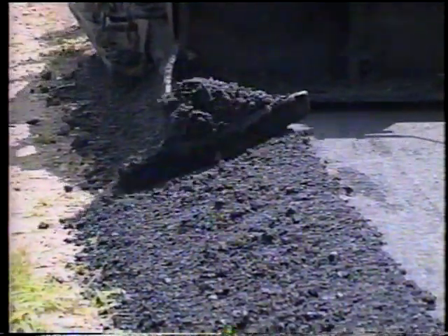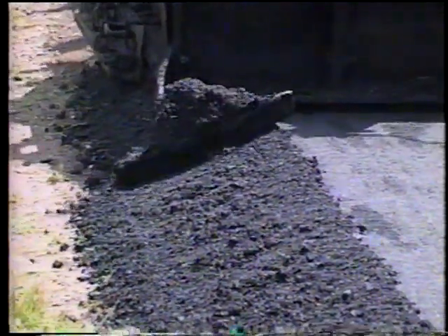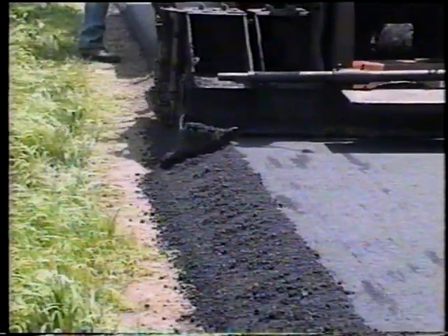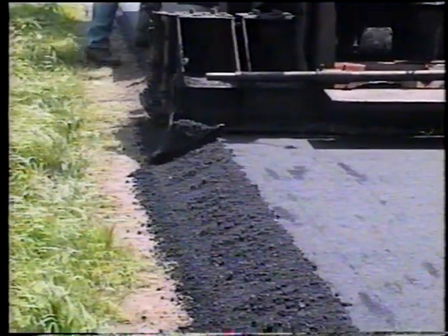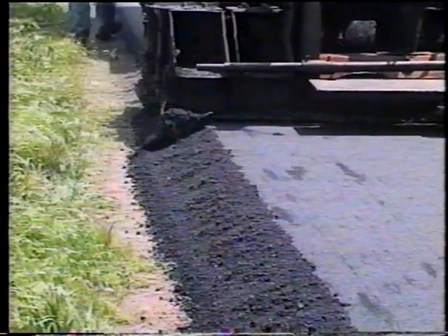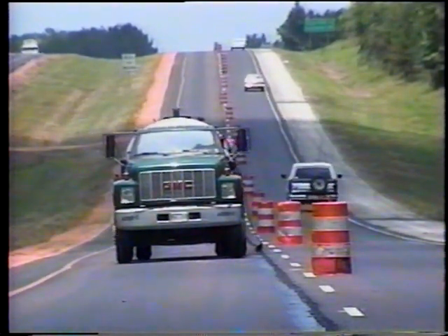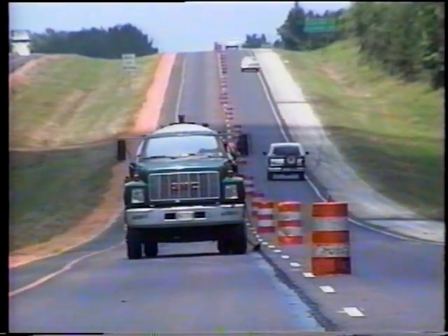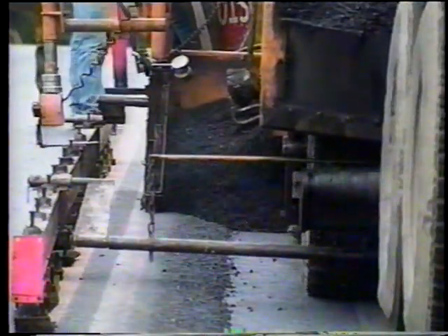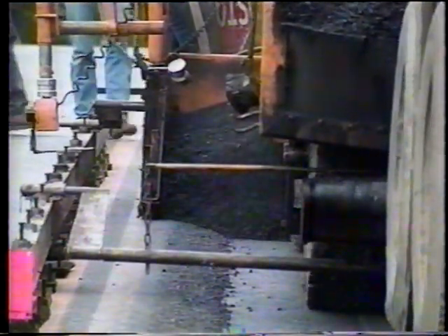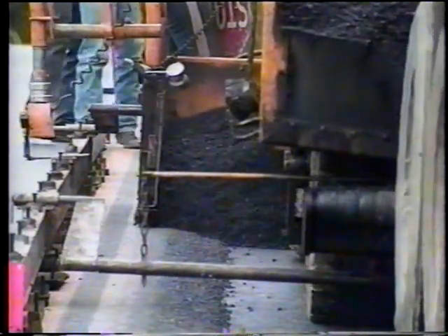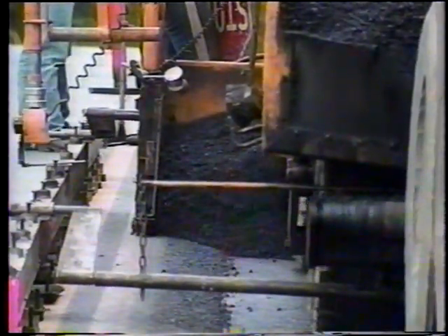Where a shoulder is paved along with the adjacent travel lane, check the shoulder slope of the new mat. The typical section sheets will identify the proper slope, normally 5 to 1 or flatter. Now, before an adjacent lane can be placed, both the surface and the longitudinal joint have to be tacked. Then, after tacking, the second lane can be paved. The paver is lined up so that there's a slight overlap into the first lane. After the paver goes by, the joint should be ready for rolling.